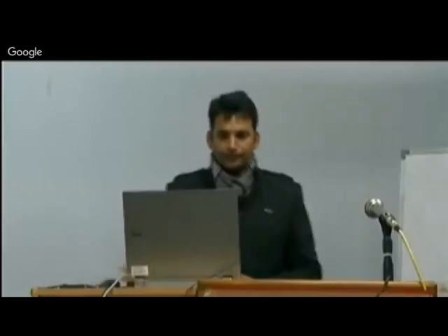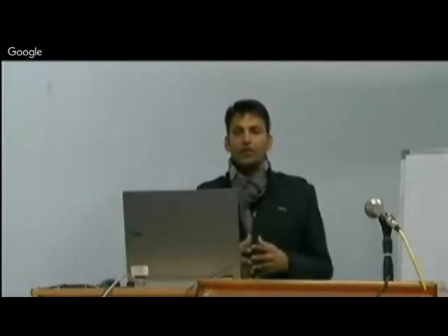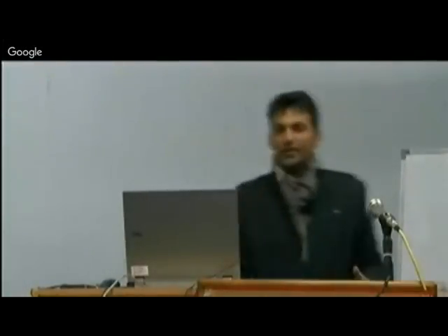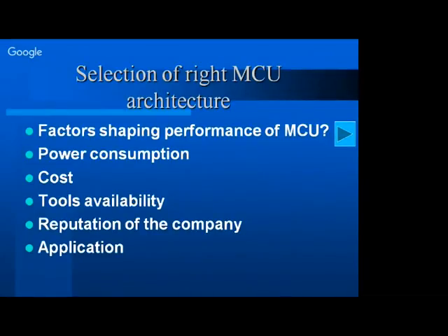So moving further, once you ensure that the quality of the performance of the controller is fine, there are some other considerations, which include power consumption. While you select the controller, besides the core, its instruction set and MIPS, you will also consider the power consumption of your controller, because the important constraints and characteristics of embedded systems are cost effectiveness, space effectiveness, and power effectiveness. So how much power it consumes will be an important consideration, in microamperes or so.